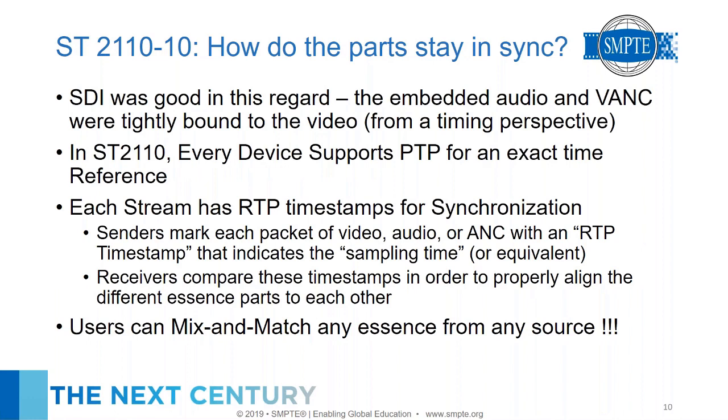2110-10, which I saved for last, is really the critical bit because it describes how all these parts stay in sync. Now, on SDI, it was pretty easy because everything was embedded together in one wire. It was all tightly coupled together from a timing perspective. So if you got an SDI, you could assume that the video and the audio and the ANC data in there were all stapled together time-wise. And if they weren't, then you went and looked at who sent it to you.